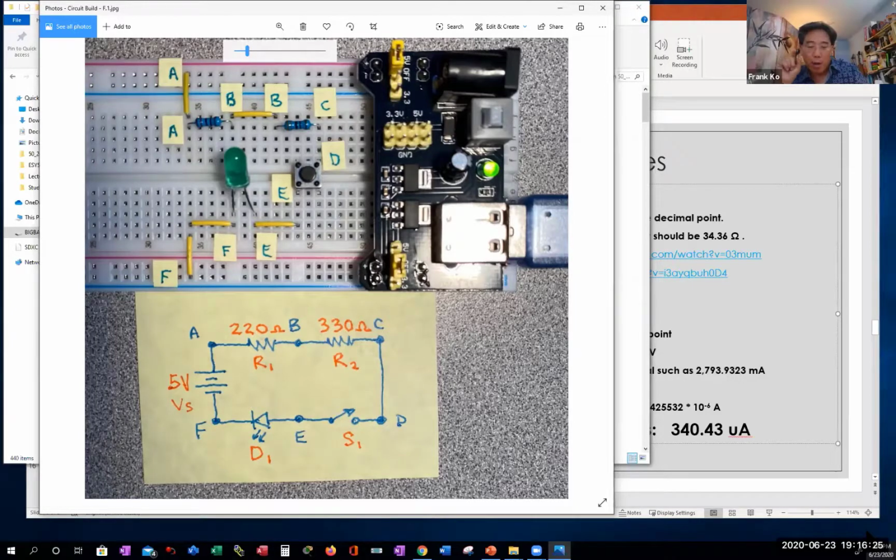All right. To answer Andrew's question, we're going to see electron current flow and conventional current flow many times during the weeks to come. Given an illustration that shows the plates of a voltage source and arrows drawn around the schematic, any arrows leaving the positive plate are conventional current, and any arrows leaving the negative plate are electron current. However it's specified is how you will answer the question, okay? Okay, all right, let's move on.